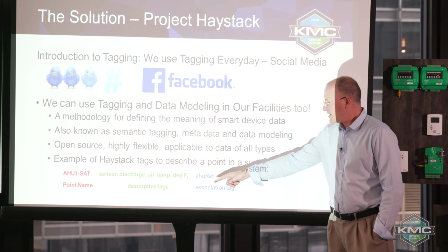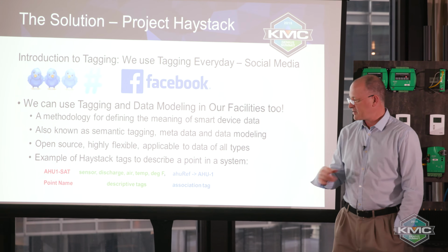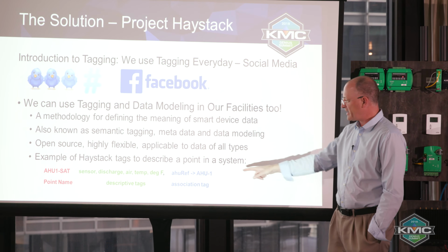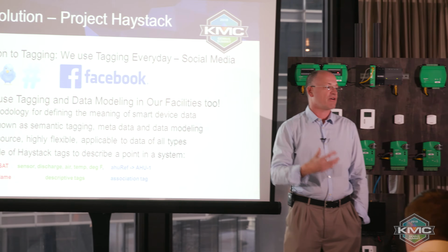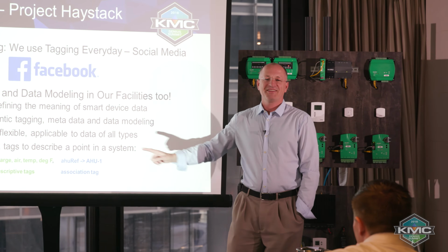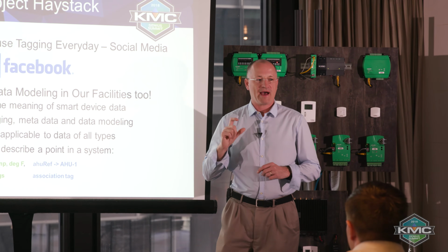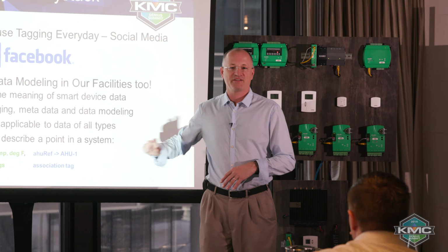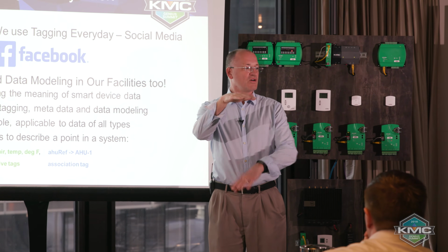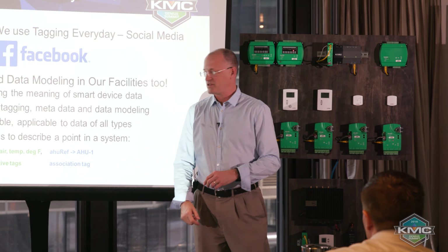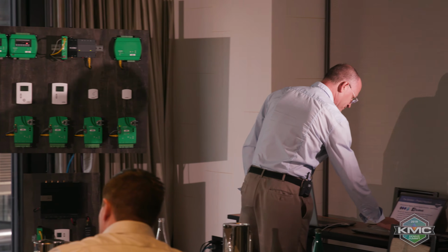I can also create that relationship like I shared with people that are friends to me, but in this case of building automation, that relationship would be called a reference tag. And so this VAV might get its air from air handler 1. So that relationship we can put in, and there'll be applications like a summary screen that could automatically show, based on a query, which VAVs are associated with which air handler. So let's take this into the real world.